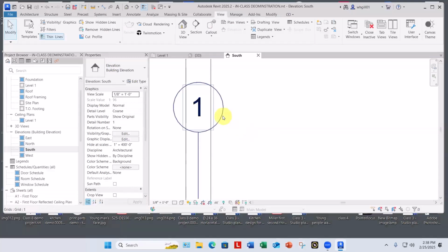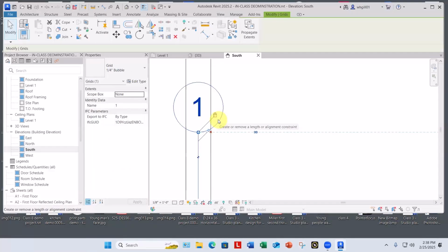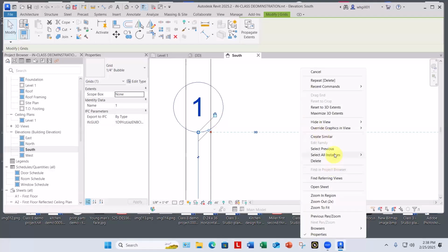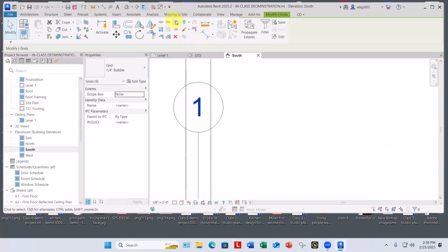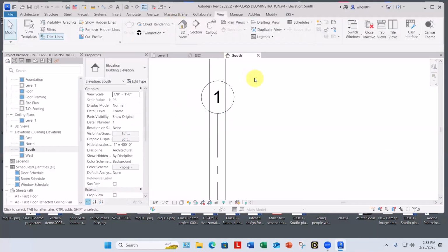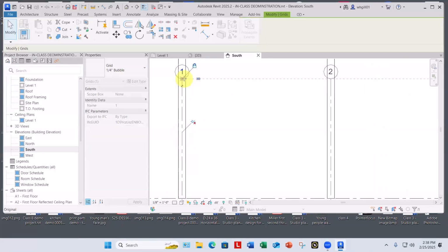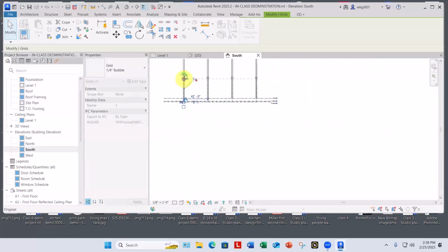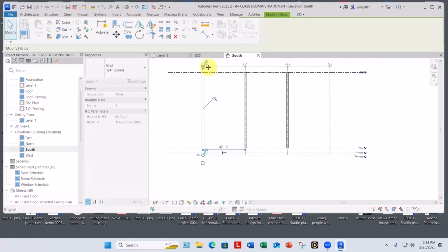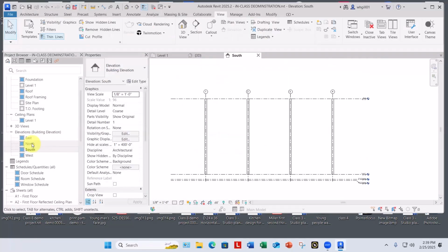If I thought this out clearly, but this gives you a sense of how you go back and forth doing stuff. So I pick one, right click, select all instances in entire project, and I'll unlock them just to get this done right. And now I can drag this button and up they go, and we'll stick them out through the top of the building.